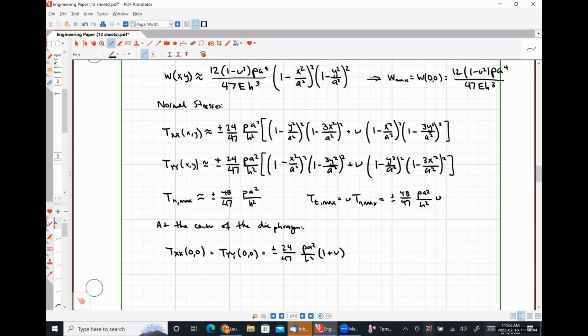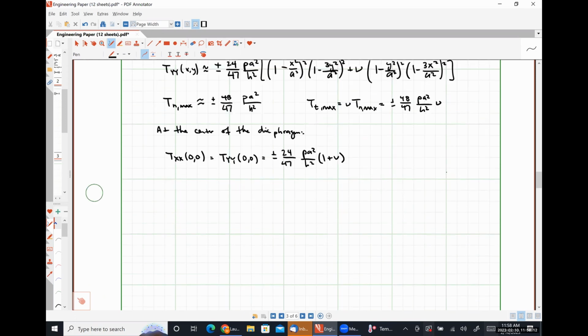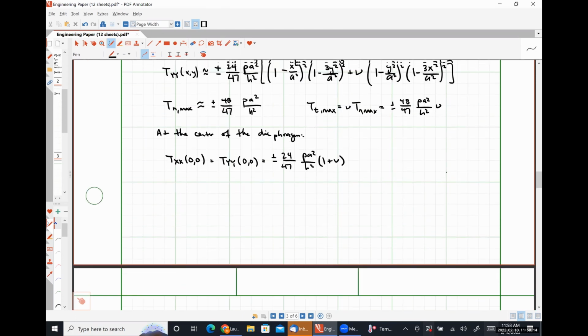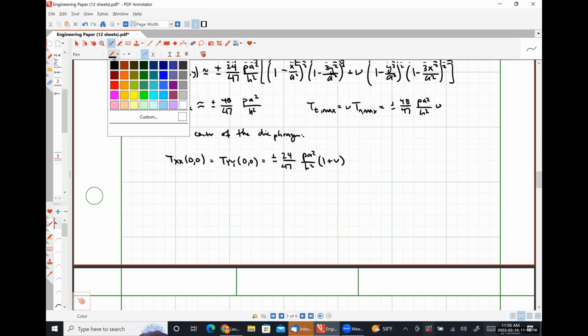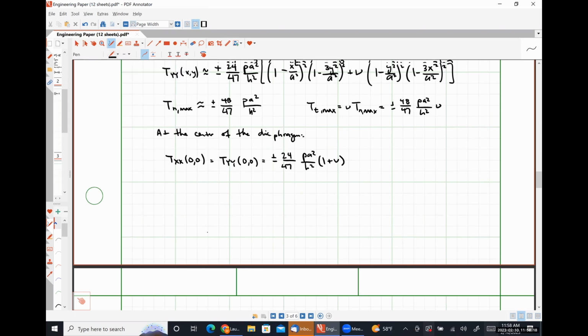So non-parallel plate capacitor, yeah, the membrane is one of your plates. So when the membrane deflects, just as a graphical thing here to show why we're not going to do the math, the substrate down here, that's one plate. And then you have your deflected membrane, exaggerated here, which is the other plate.